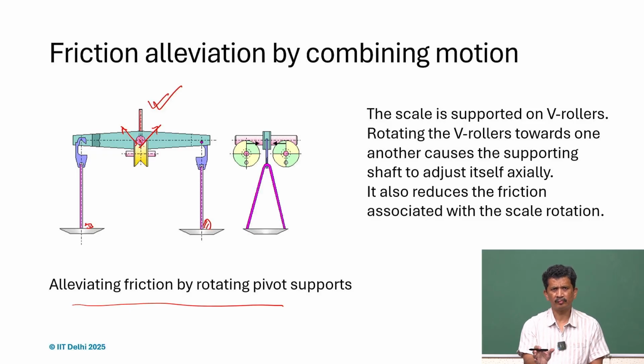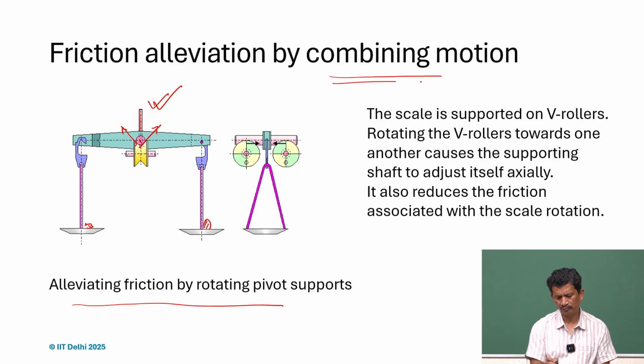and it's a zero, but it's not zero because it can always get stuck at a certain location if it's within that virtual play. Similarly, here also it can get stuck, and that amounts to the error in the measurement. So if you want to minimize that error, we can always use that combined motion.